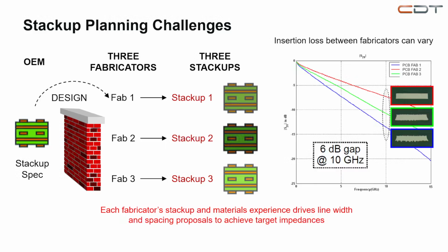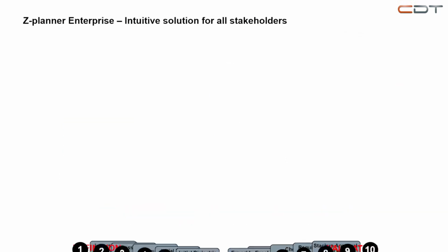The answer to the why is that they were using different copper roughnesses and different oxide alternative treatments and many other small assumptions they made to fit your requirements. At 1 GHz, these differences would be almost zero, but at 10 GHz, in the multi-gigahertz range, it will have a significant effect. One of the biggest challenges companies have regarding stackup planning is communication and collaboration with PCB fabricators.